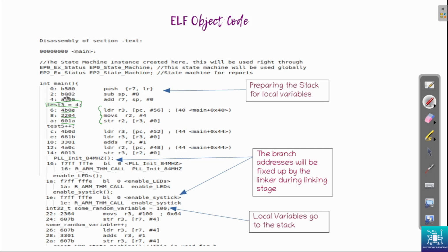See, there are 16-bit values. So the address location starts from 0, then 2, 4, 6, 8, and so on. The program counter starts from 0, then it will be 2, 4, 6, 8, and so on, because all these instructions are 16-bit instructions, or 2-byte instructions.